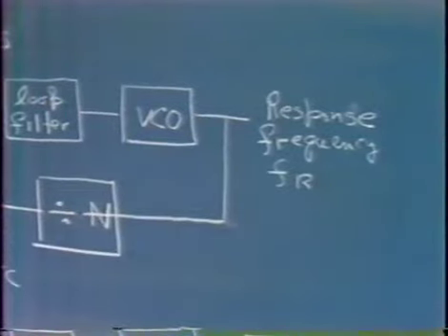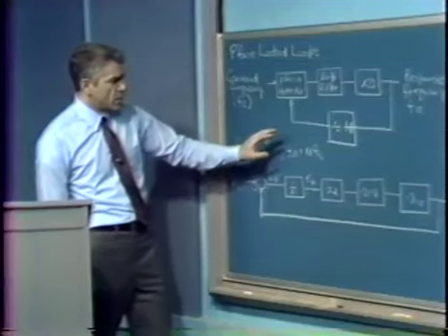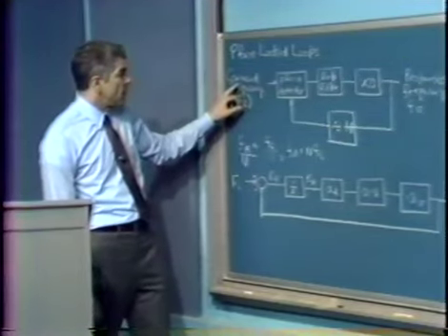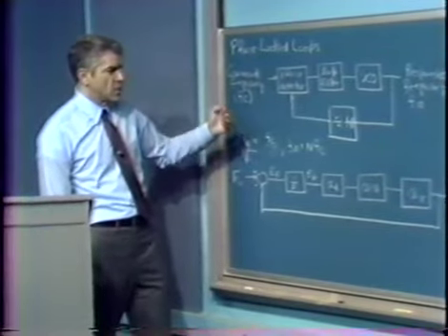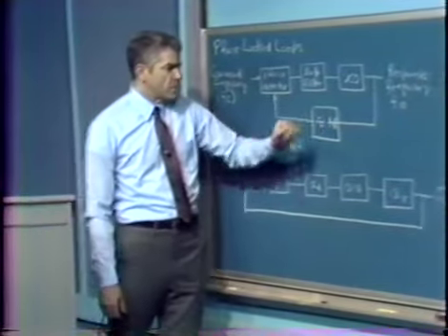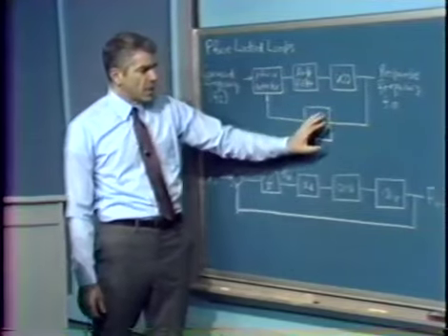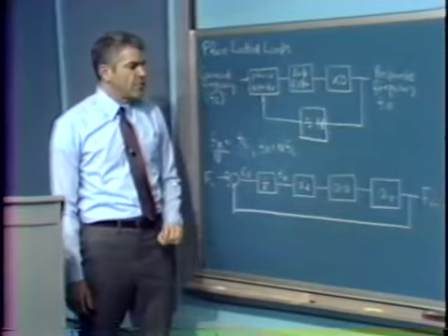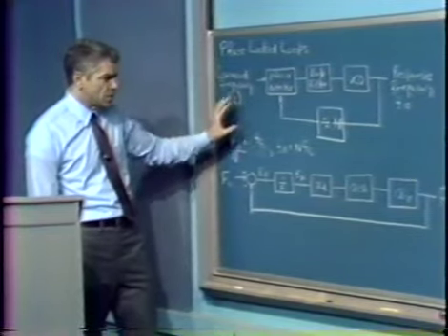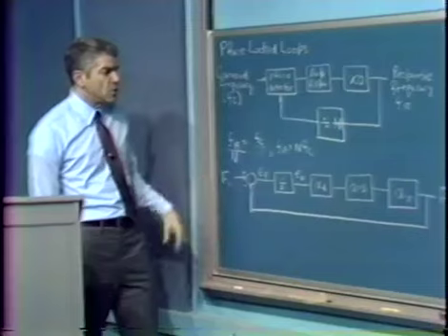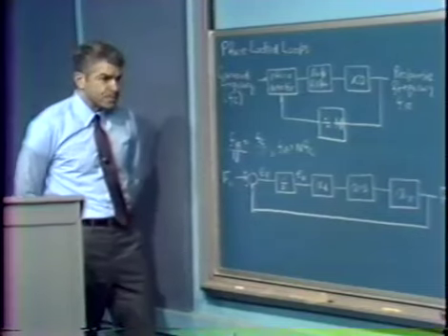Consequently, we can generate with a resolution dependent on the frequency of the command signal. With that sort of resolution, since we get integral multiples of that frequency at the output, we're able to generate multiple frequencies, each of which has the same stability as the command frequency. And so this technique is used in frequency synthesizers.